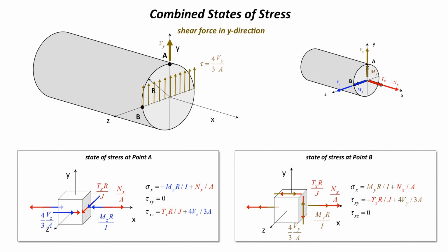Whereas if I now put a shear force in the y direction, it's just the opposite. The maximum shear stress is occurring on that axis, which is Z. So I'm going to be putting on the 4/3 Vy over A like this. But being as A is on the outer fibers of the beam in the direction of the applied shear force, there's no contribution there.